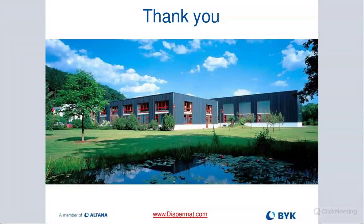And there are some key things we look at, like I said, screen size, mesh size, the quality of the material that we use for the milling disc, ceramic, blade diameter, all these things. Then we talk about the processing parameters, the amount of energy we are putting in, the tip speed. All these things should be constant when we go to production. And we should be able to get very close results to what we get in the lab.